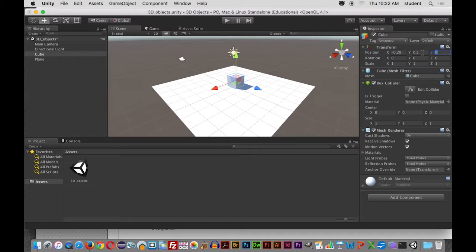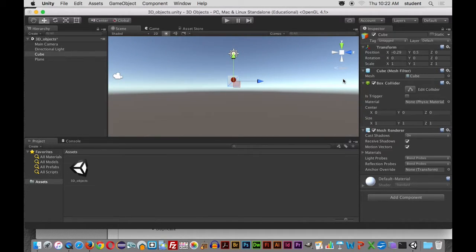So this is what you did. Up here, right here, you must have accidentally clicked that. So what you do is you right mouse click here and select free. Remember those 4 different views that we were looking at before? Top, right, left, and so on. Basically we can see that in this particular view, so we can change it just in this view. I can change it to right view, and notice that's what you have right now. You see? We're looking at just the right side of those 2 objects.